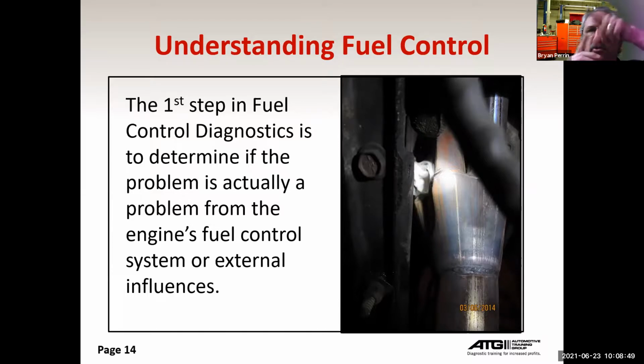So you don't want to just grind it and make one little squiggly line. If I'm welding a cracked exhaust manifold, I'll lay one line down and then a line on each side, so there's a minimum of three lines. One is the actual crack, and then one on each side of the crack to tie my weld into an area that's further away from the metal that failed.